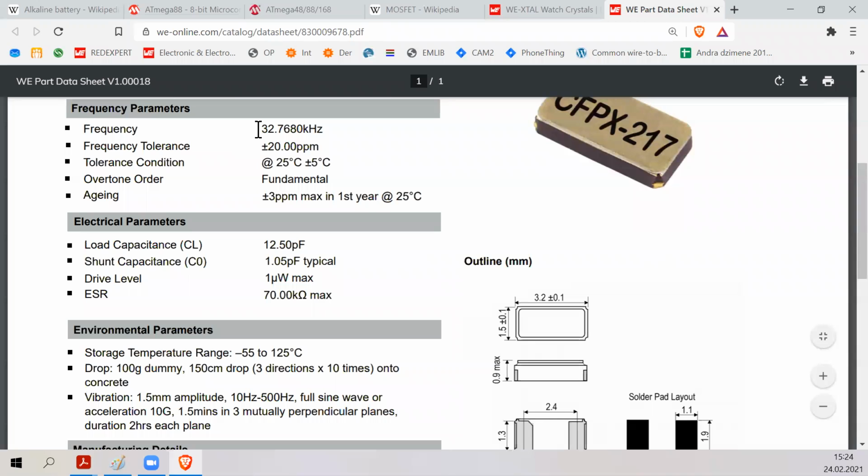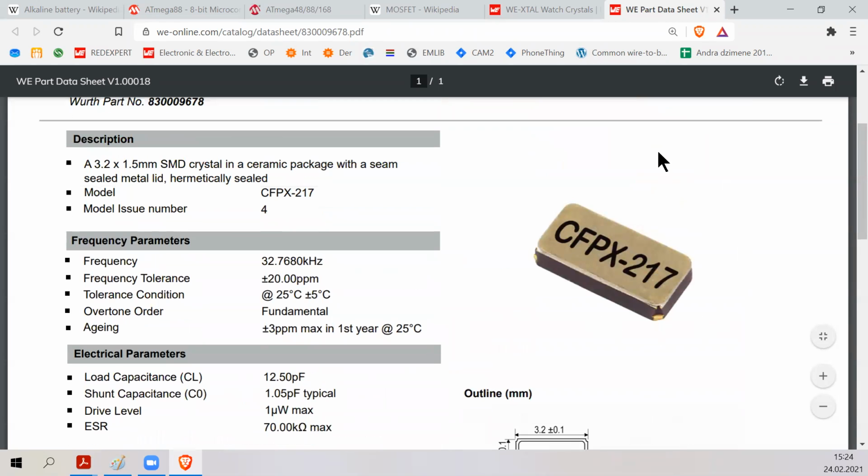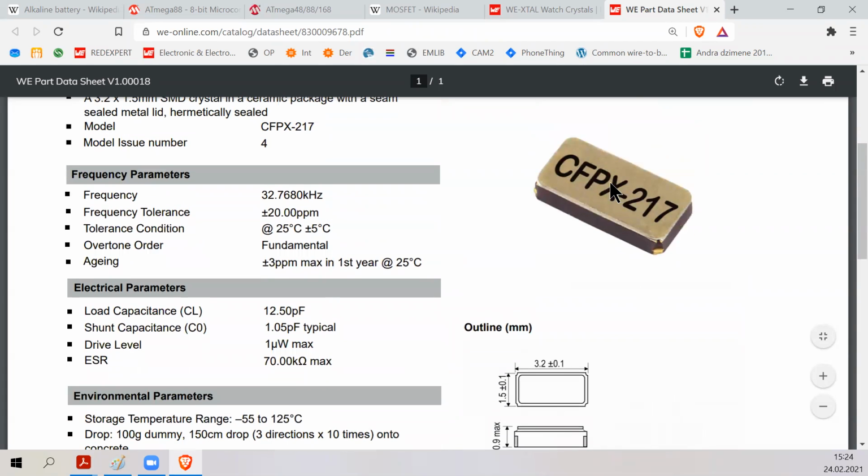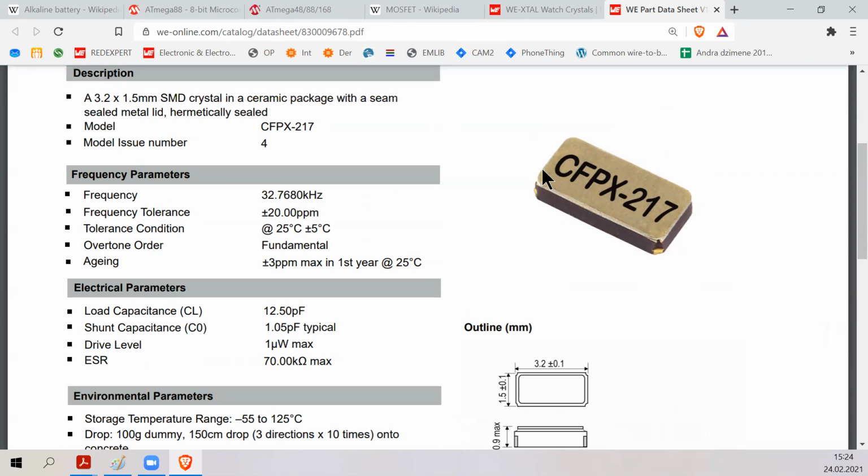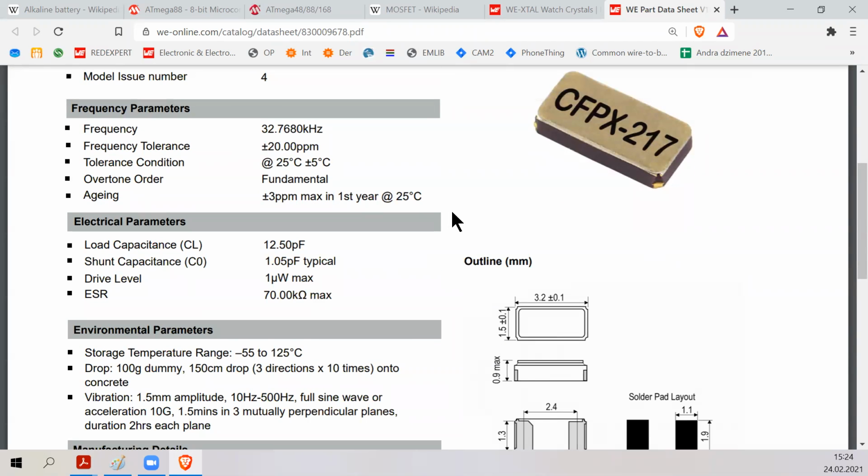If you wanted to make a crystal which has internal resonance frequency at 1 hertz, it would be very, very big in size. As you know, the bigger the material, the lower the frequency. So this was a good size and good frequency fit historically.